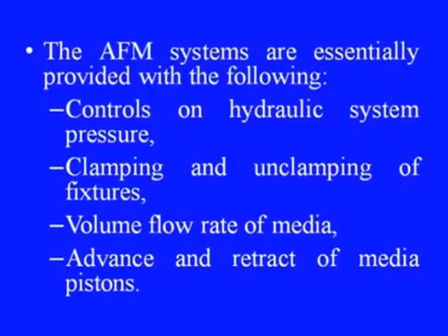The AFM systems are essentially provided with controls on hydraulic system pressure, the clamping and unclamping of the fixtures, the volume flow rate of media, and the advance and retract of media pistons.